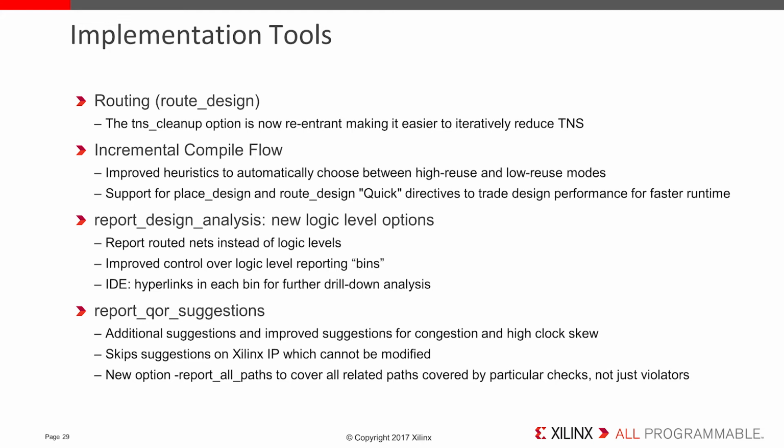There have been miscellaneous enhancements to report design analysis as well. Notable additions are in the logic levels reporting. There are new options to replace logic levels with routes, which tends to be more representative of the critical path. Options to specify the bins for logic level reporting, and in the GUI, the logic level report table now is hyperlinked to allow drill down analysis into each logic level bin.